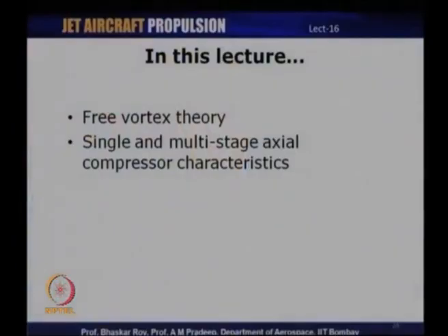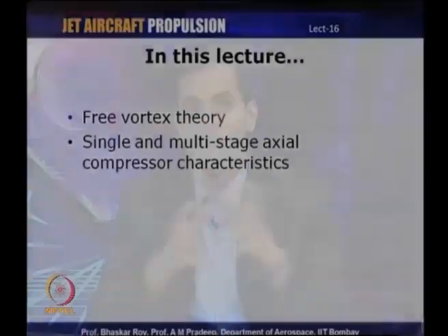So, let me wind up today's lecture, wherein we were discussing two important aspects. One was the stage characteristics, the single stage characteristics, as well as the multi-stage performance characteristics of an axial compressor. And the other aspect was the free vortex theory. We started the lecture today with some preliminary discussion about the free vortex theory and how it can be used in preliminary design of axial compressors.